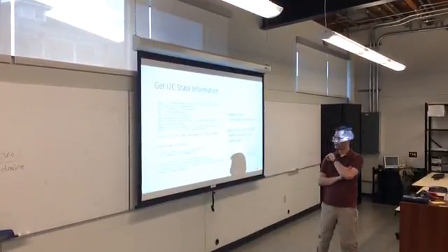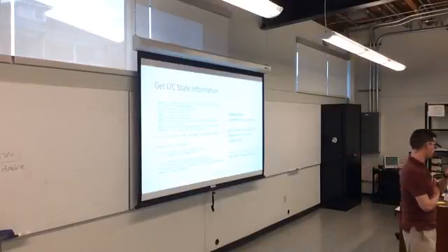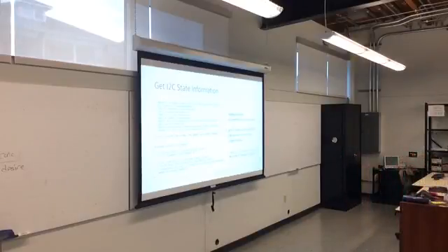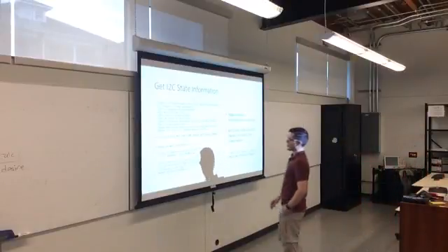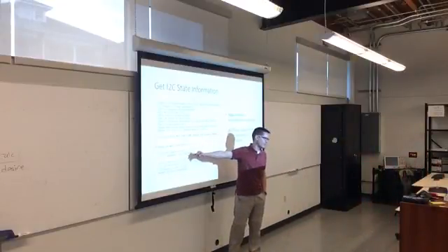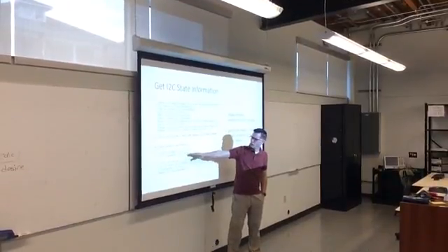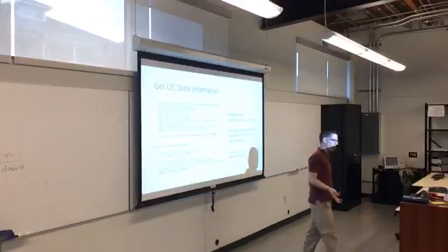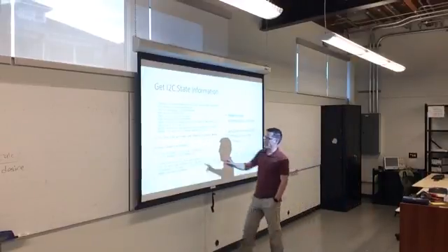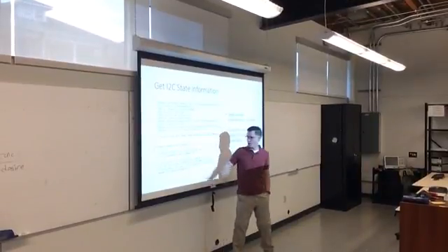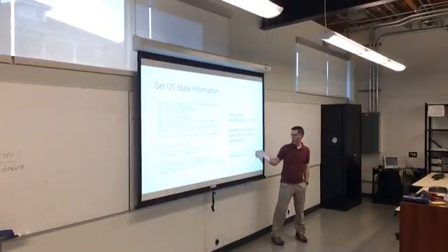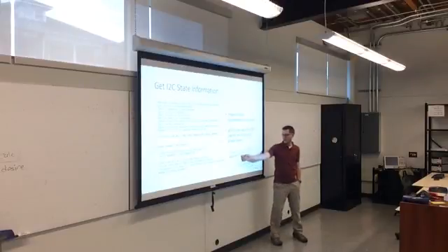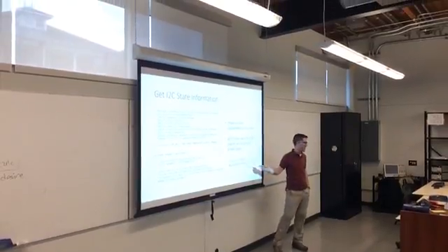of the bus. So one of them is a function that returns those little state bits inside of the state register. Those bits get cast as an enumeration. What that means is you can call a function called get I2C state, and you will get one of these words back. So if you're going to wait for the bus to become idle, you can say get this state here while the state is not idle. So what an enumeration does is it basically replaces this word with a number. So this is 0, 1, 2, 3, 4, 5, 6, 7.